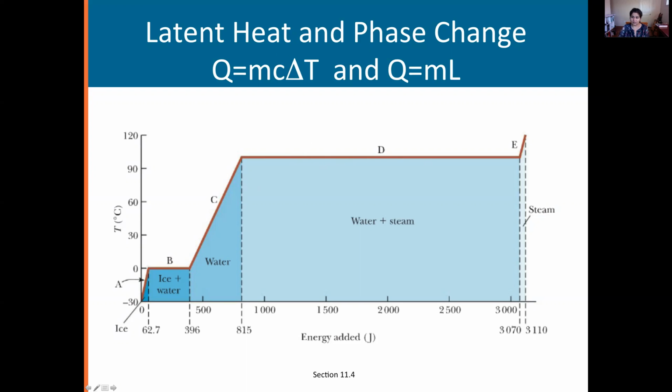Once you reach 100 degrees Celsius and all your water has turned to steam, you are at this point. Now, at this point, you had 100 degrees Celsius, everything is water. Some part water, mostly water, some steam, about 50-50 water and steam, less water, more steam, all steam. That's how you're progressing along this line. Once you have steam at 100 degrees Celsius, if you continue to provide energy into the system, you're now going to get superheated steam, which is this portion E of the line going upwards, very steep slope.